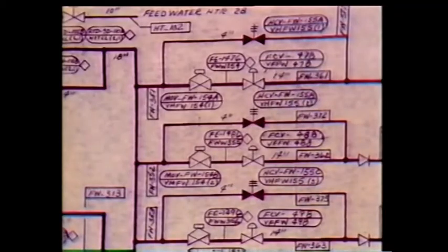Flexible hoses are available in 3 general pressure ranges: low, medium, and high. When hosing is selected for a particular location in a plant system, pressure and vacuum ratings must be considered. In addition, environmental conditions, especially temperature levels inside and outside of the hose, will also help to determine the type of hose that is best suited for the job.